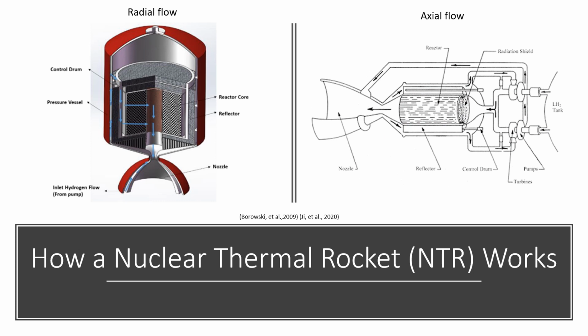Hydrogen being used as the medium for heat exchange starts its life as a liquid at approximately 20 Kelvin and is pumped firstly to the rocket nozzle. It follows coolant channels around the extremities of the rocket, passing over the shear wall and onward towards the reactor core.